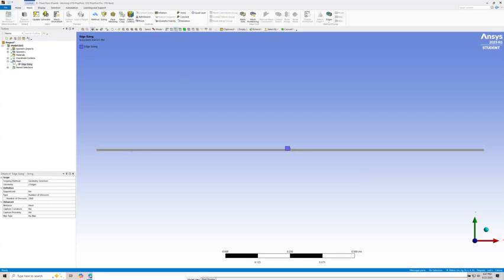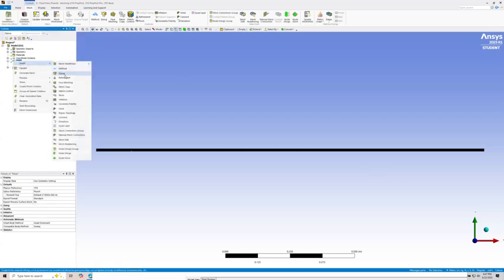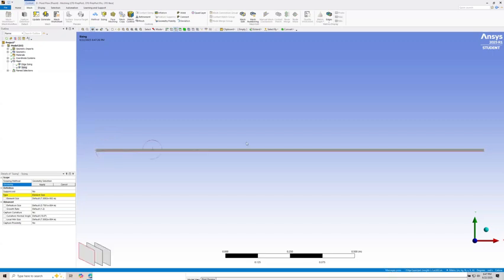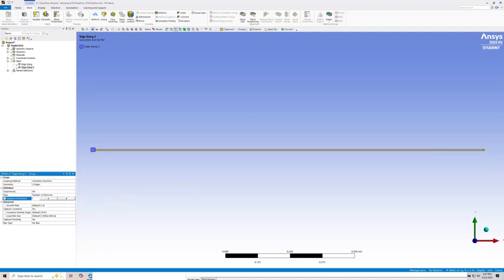Alrighty, so there's our first mesh. We're going to go back to mesh. We're going to insert another sizing mesh. Like mentioned, it's going to be between our inlet and our outlet. Make sure you apply that geometry, switch it to number of divisions, but since we're going to change this one, for this one we're going to do 100 divisions. Not going to capture the curvature again, and this one's going to be a hard behavior. Once you have all that done, you can press generate, and then we have to wait yet again.